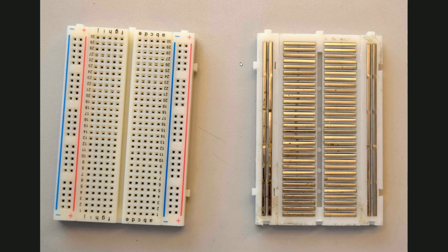You may note some vertical lines in the left and the right part of the breadboard. And the reason is that usually we use these vertical lines to provide power to my whole circuit. Remember, positive and negative. So usually we connect the power source here on negative, here on positive, and then I can get positive connections and negative connections in every single hole from this line.